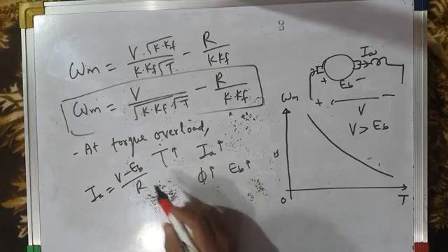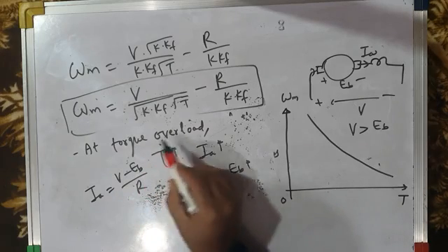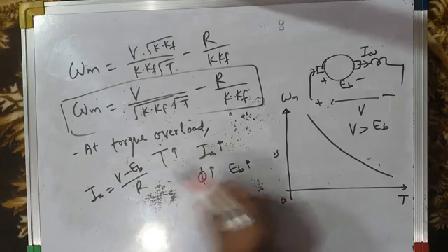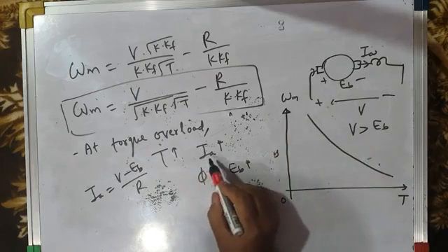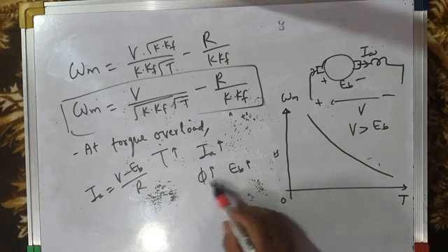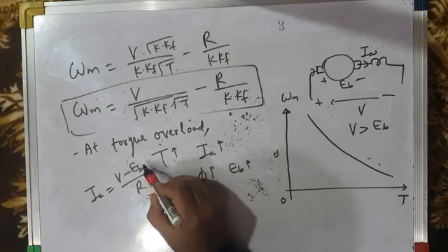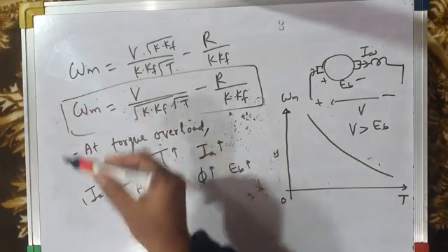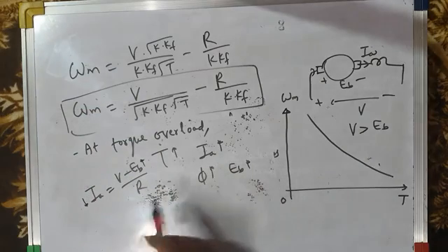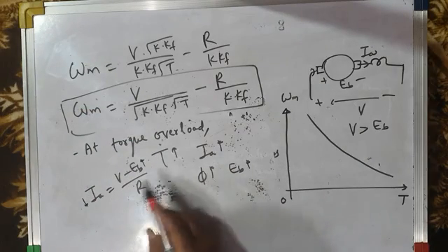So when there is torque overload on the motor, the armature current may temporarily become very, very large. But when the armature current increases, the flux increases, and that increases the back EMF. So the armature current, which had temporarily increased, will come back and be maintained within safe limits.